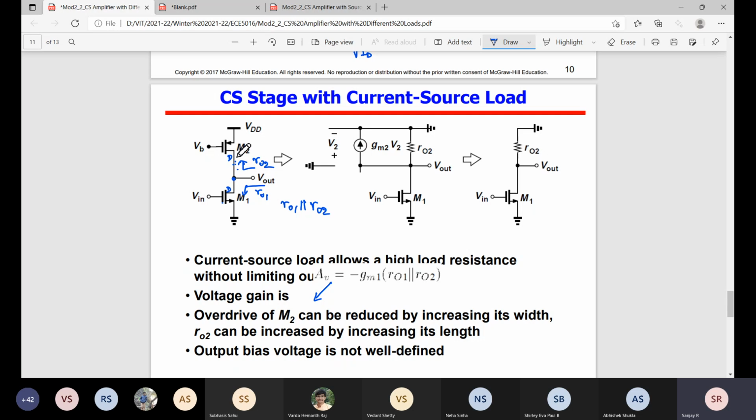So it is always not recommended to connect two things to establish that node voltage. We will use a common mode feedback circuit; that we will study in op amp. So always remember, when you connect both NMOS and PMOS drain nodes together, that potential is not a constant thing. It will vary, depending on the current values in NMOS and PMOS, so it will randomly fix to some value. To fix the drain voltage to a known voltage, we have to use common mode feedback.